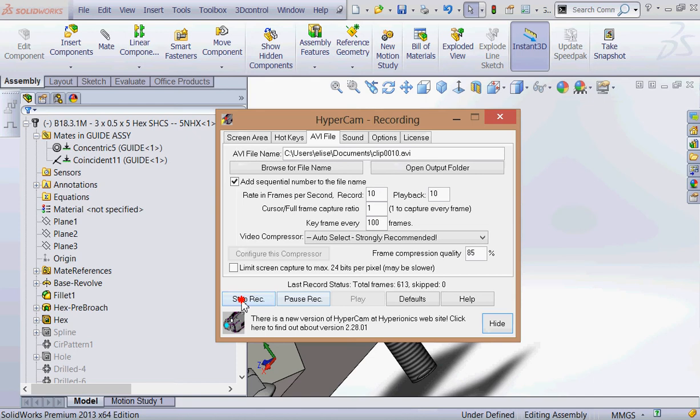Notice it previews, and you see where it says select seed position? That shows me where the pattern is, so I know this is the seed feature. That's my workaround: if I didn't place it in the right place, I could just tell it which one's the right place. And then I green check.